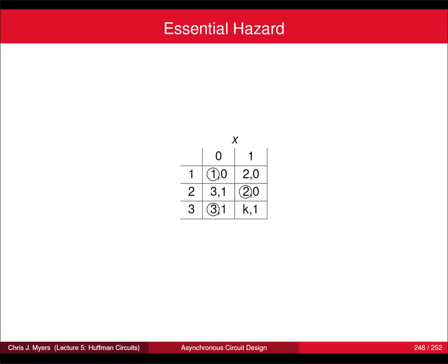If the input changes again too fast, it's going to output a 1 momentarily. So what we need to make sure is that there's enough delay in the feedback that you don't have the state variables change, feed back and change, and actually have you move down a row till the output's stabilized. Because otherwise you could have glitching on the output, these sequential hazards.